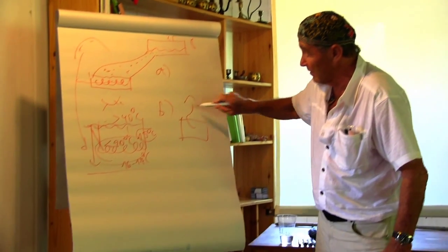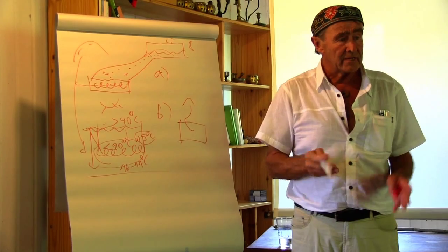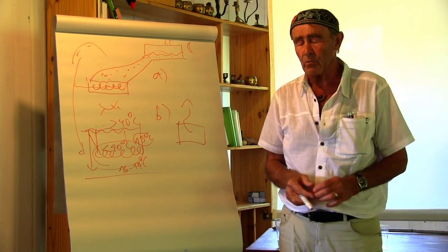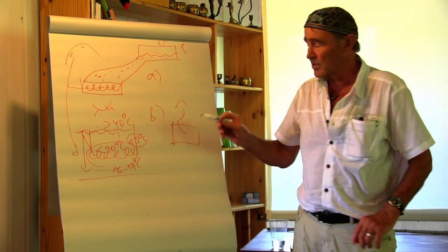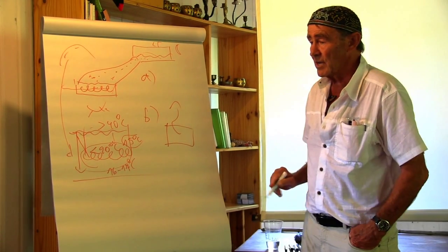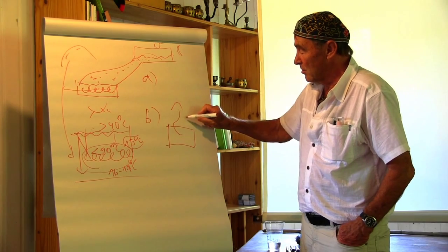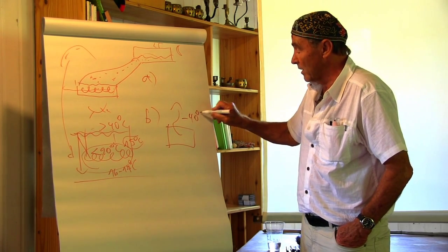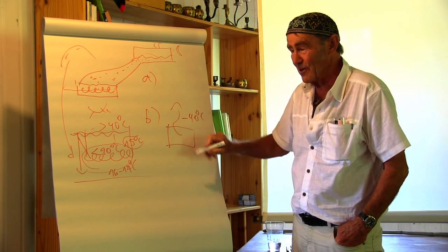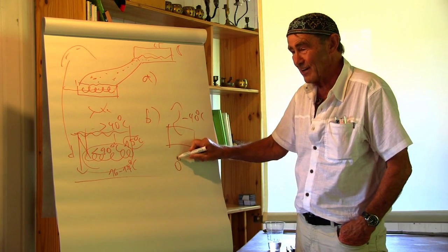Of course, one must know that per square meter we have about 100 watts of radiative cooling. And I'm not going into details. It has to do with the atmospheric window between 8 and 14 micrometer. But the potential is that this cools down in an ideal case to minus 40 degrees centigrade, and the reality is it cools down to around 0 degree.